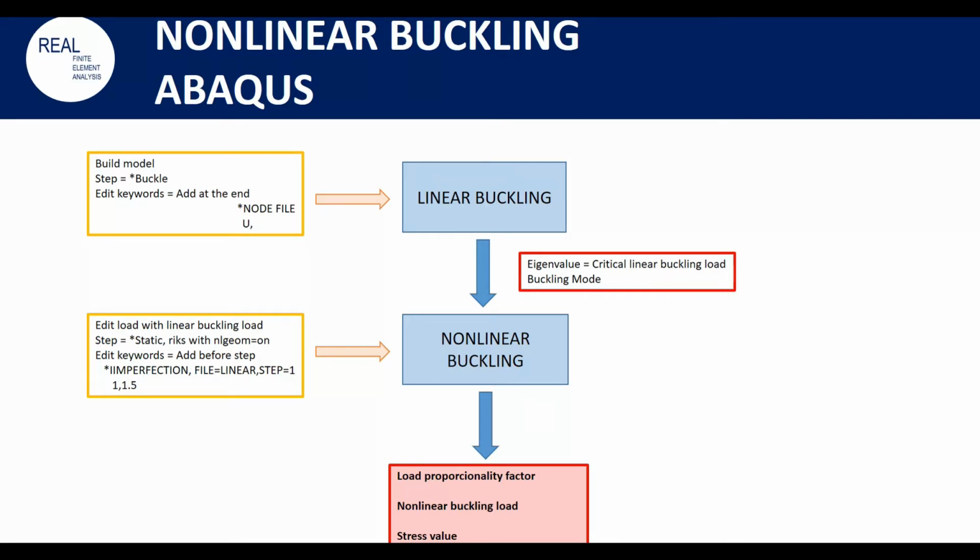So that is how the mode is contributing to the final results, in order to get stresses and the load proportionality factor, and therefore the nonlinear buckling load. So those three will be the outputs from the nonlinear buckling analysis. So we'll get the load proportionality factor, with that we'll get the nonlinear buckling load, and therefore the stress values on the geometry.